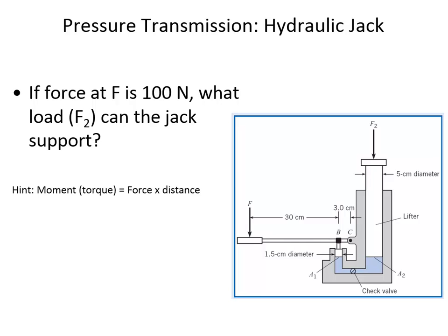What's the pressure inside of the jack? There's probably a hydraulic fluid in the jack. How can we find out what is the pressure, the liquid pressure inside that jack? Good, right. So remembering that force is pressure times area, if we want to know the pressure of this fluid, it's going to be the force divided by the area. And so 11,000 newtons is the force that this little plunger is pushing on the fluid with.